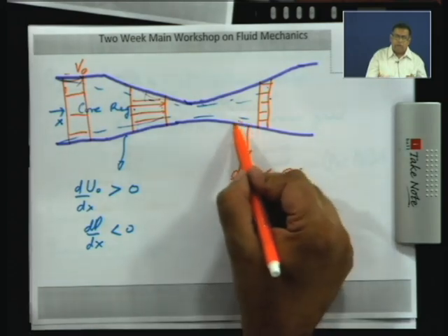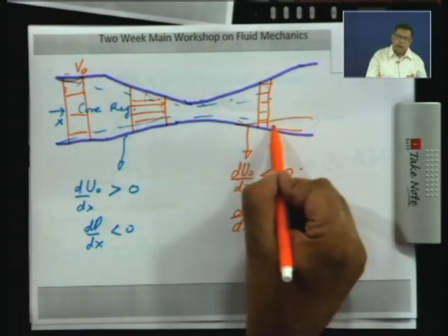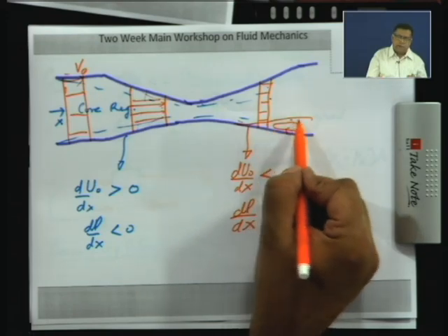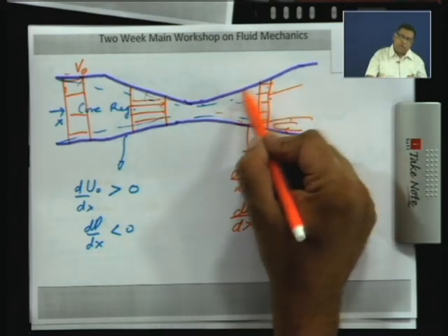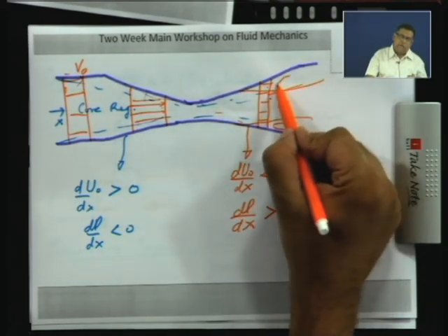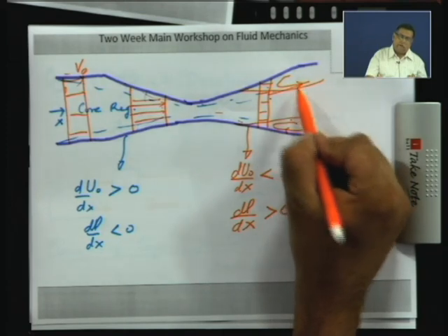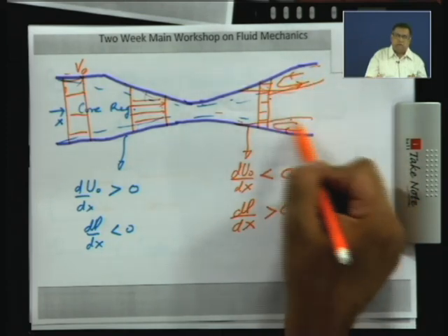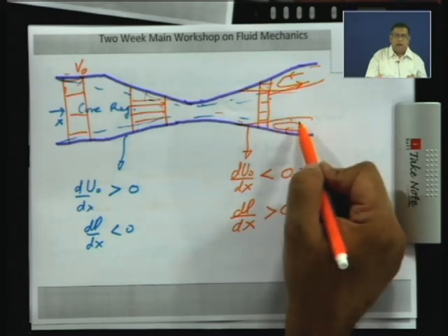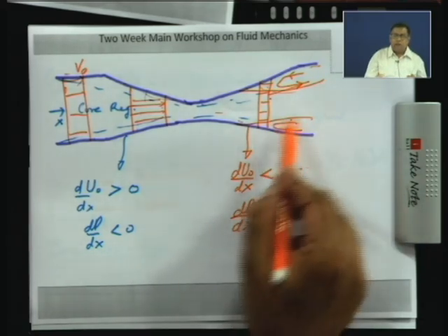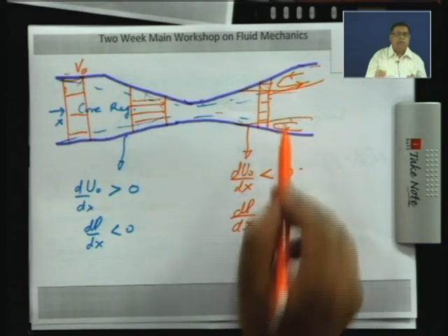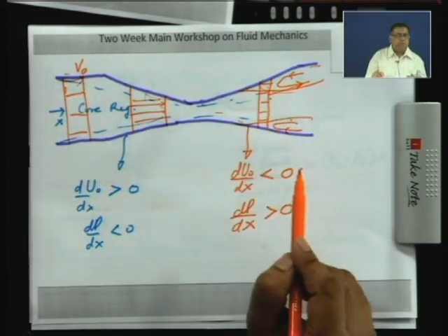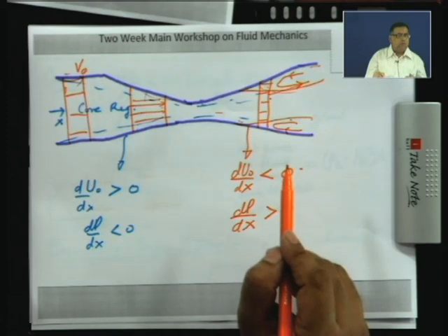And what might happen is the boundary layer might separate and you may have a flow inside the diffuser which is in the opposite direction to the main flow. So, if this is a point of separation over here, the fluid may come in the opposite direction and move over here. So, you have what is called a flow reversal, and once you have a recirculating region over here, there is some kinetic energy associated with that. So, the losses will increase, and that is what you want to avoid.